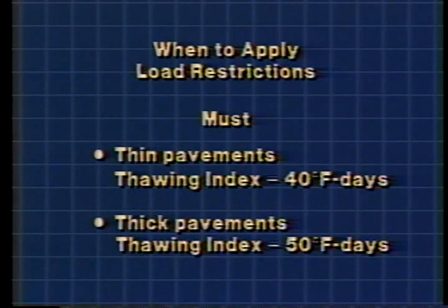These criteria are best suited for use during the normal start of the spring thaw period, generally late February to April, and they are best applied to fine-grained subgrades such as silts and clays.